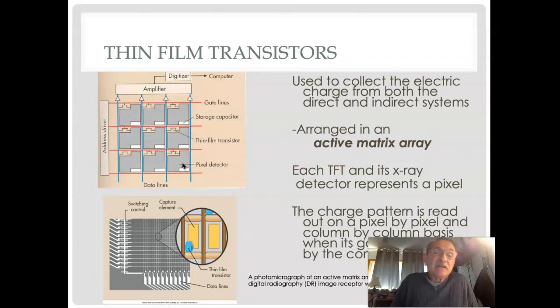Okay, and notice that it says on the left side of that illustration, I have an address driver. I'm seeing a matrix here of 3 by 3, which is 9, and that address driver will recognize and keep track of pixel number 1, or position 1, column 1, has a certain value, and then row 1, position 2 has a different value, and 3.